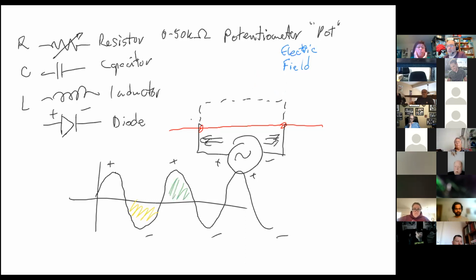So this is really important, because when a capacitor encounters a DC voltage, it charges up and then doesn't take any more because there's no more room. When a capacitor encounters an AC voltage, it acts like it's not even there. It just becomes a short circuit. It allows the voltage and the current to flow back and forth.